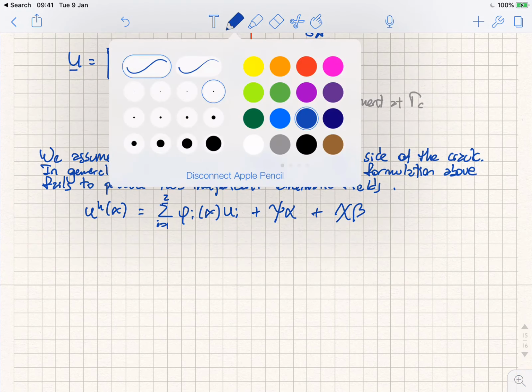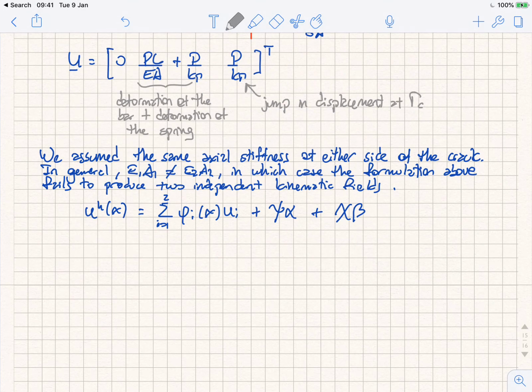So now if you see my DE-FEM formulation, general DE-FEM formulation has 2 enriched terms. This one is taking care of the weak discontinuities, and this one here is taking care of the strong discontinuities. And this is great because if you're solving a problem and you don't have a strong discontinuity, your formulation falls back to the IGFEM formulation.